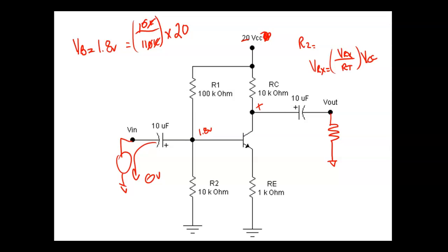So right now, here's 0 volts down here. Here's plus some voltage. So that means we'll put the plus toward the collector. So that's plus DC, right? Over here, this is seen as 0 volts as a DC reference, right? So I'm putting AC over here. What's the DC average of an AC sine wave? 0. So that means this capacitor is not seeing this as AC, it's seeing it as 0.